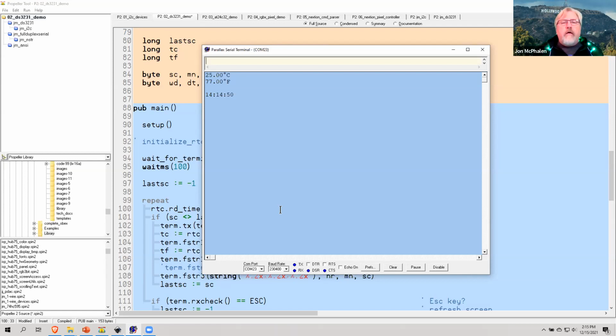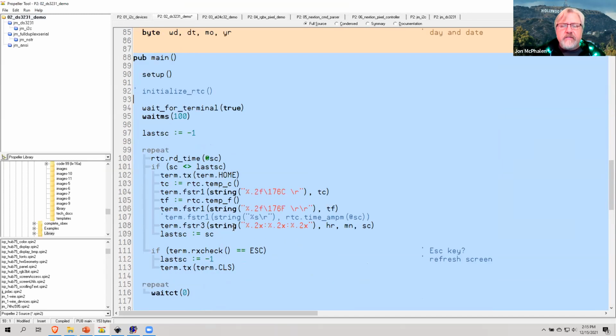Yes, okay. I was wondering why I was getting 14:14. It's because it's 2 p.m. But here you can see that I'm running the clock. Now this is 24-hour mode because I didn't do the conversion, but it's because I'm treating those values as hex. So bear that in mind when you're doing displays. It's pretty easy to deal with writing the registers directly.